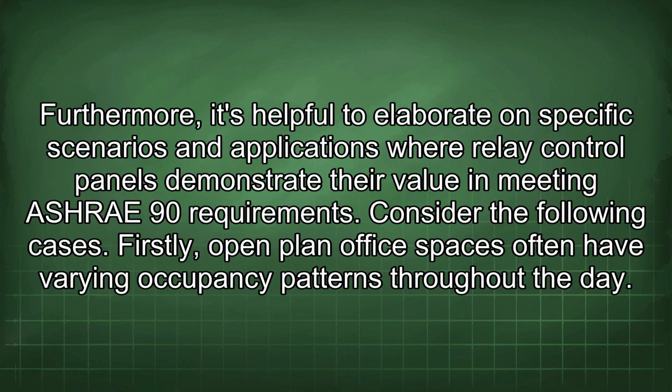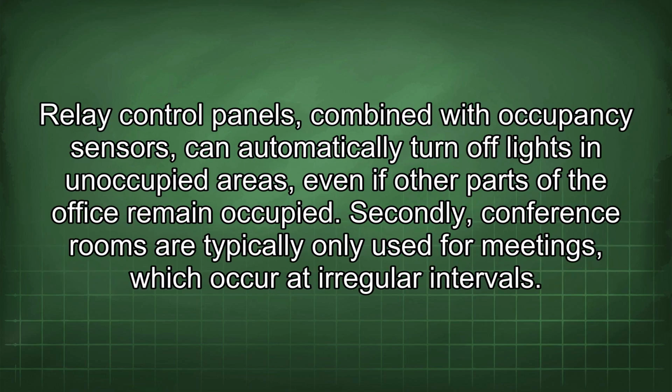Furthermore, it's helpful to elaborate on specific scenarios and applications where relay control panels demonstrate their value in meeting ASHRAE 90 requirements. Consider the following cases. Firstly, open-plan office spaces often have varying occupancy patterns throughout the day. Relay control panels, combined with occupancy sensors, can automatically turn off lights in unoccupied areas, even if other parts of the office remain occupied.